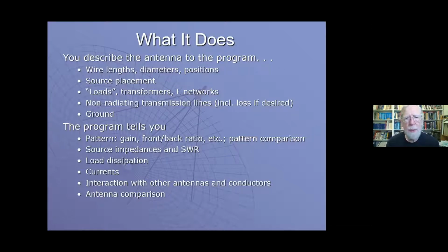You can find where the currents are on the antenna and on other objects around the antenna. You can find the source impedances, the SWR, what you want to know about the loads, dissipation, and so forth. It's very good for assessing the interaction with other antennas and conductors.